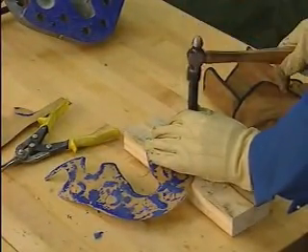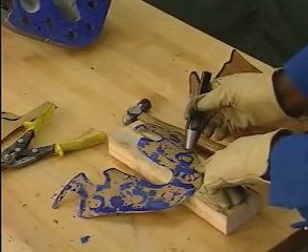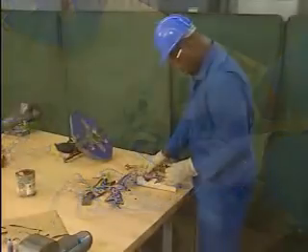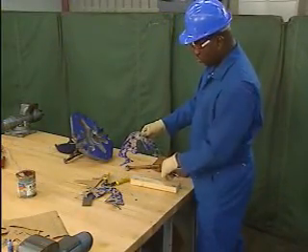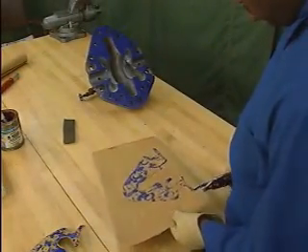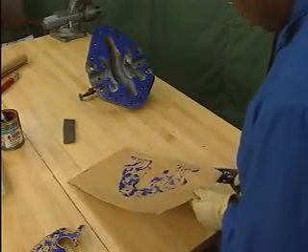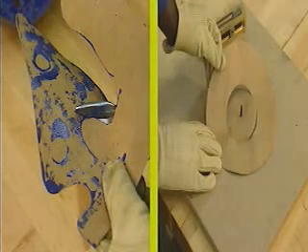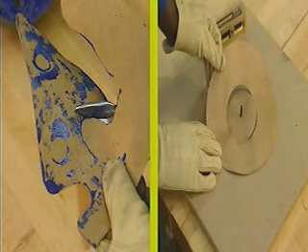He then strikes the punch with a hammer to make the hole. The process is repeated for each bolt hole in the pattern. Once all the bolt holes have been punched out, the gasket is ready for installation. The mechanic then cuts the other gasket for this pump following the same procedure. We've seen two ways that gaskets can be cut. Now try a question on cutting gaskets.